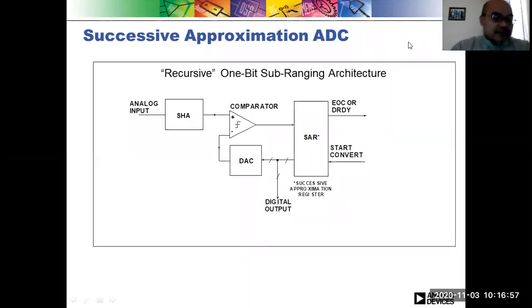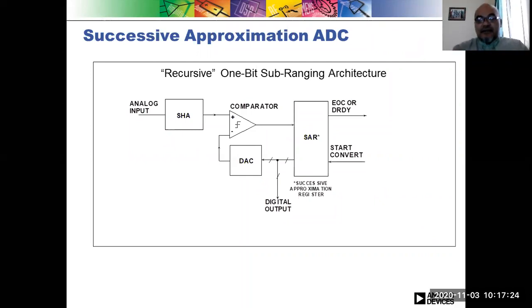So today we are going to discuss the different algorithms or architectures used in an analog digital converter to convert an analog signal into a digital signal. The first one, which is quite popular, is called a successive approximation analog digital converter. As the name implies, the architecture of this ADC tries to approximate the analog signal closer and closer according to the bit.